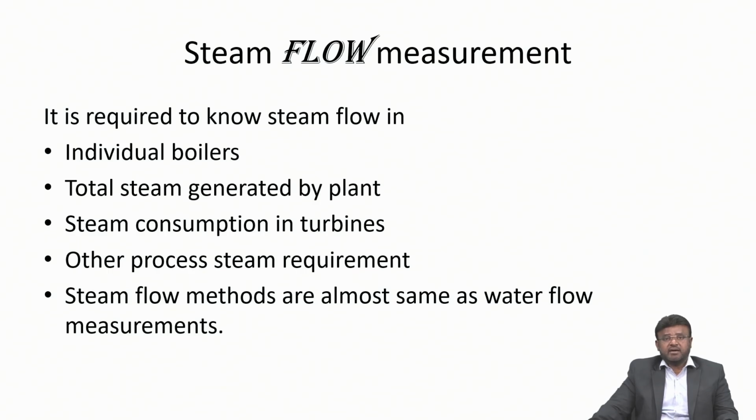Normally, thermal power plants are designed with a larger number of boilers instead of a single boiler. Boiler stages 1, 2, 3 and so on, depending upon the capacity of that particular plant, we have more boilers. These boilers individually generate steam depending upon their TPH value, that is nothing but the tons per hour range. All this generated steam is collected at one point or one unit. This unit is called the steam bus.